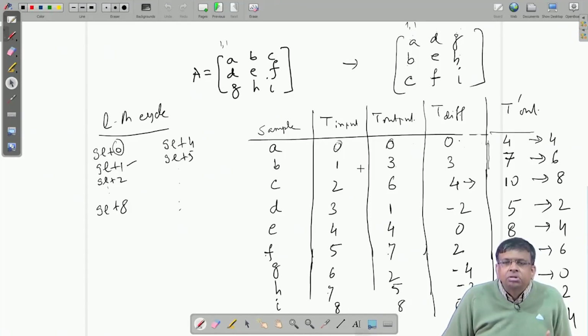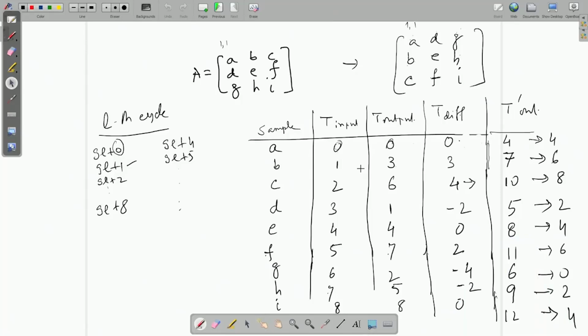Then we asked the question: who will give you the description of the lifetime of the variables? If you consider a variable, say A, in which cycle is it born, which cycle is it dead, and what will be the period of the system? Because this will be periodic, the same phenomenon will occur again and again. So, for all these you have to carry out what is called the lifetime analysis of the system. That is, you have to investigate what the variables are, in which cycles they get generated, in which cycles they get consumed, that is they become dead, and for how many cycles they remain alive, that is, they need to be stored in some delay registers, and what the period of the system is.